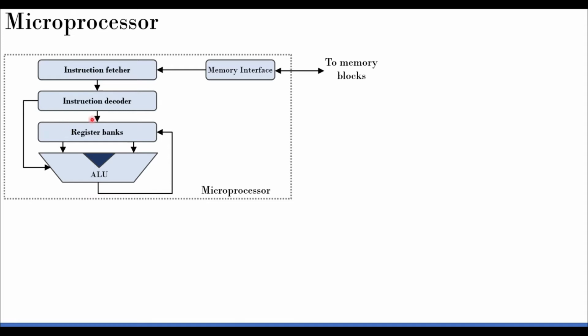And then of course there is very minimal memory. That is the important striking point. We do have a bank of registers. In our small 8-bit microcomputer, we talked about register A, which is also known as the accumulator, and register B. So we only had two registers, and then some small registers like the memory address register and the output register. Those are the register banks I mean. But a modern day microprocessor, for example the Cortex M0 Plus that you are going to learn, has a bunch of registers, something like 8 registers to play with. That's what we mean by register bank. This constitutes the only memory available to the microprocessor unit.